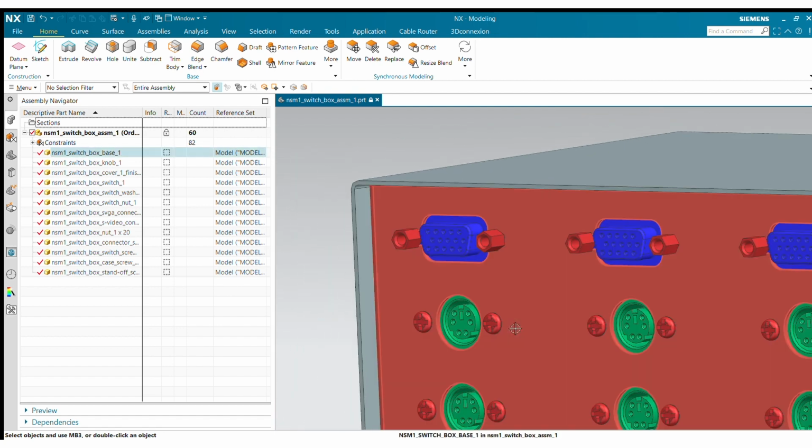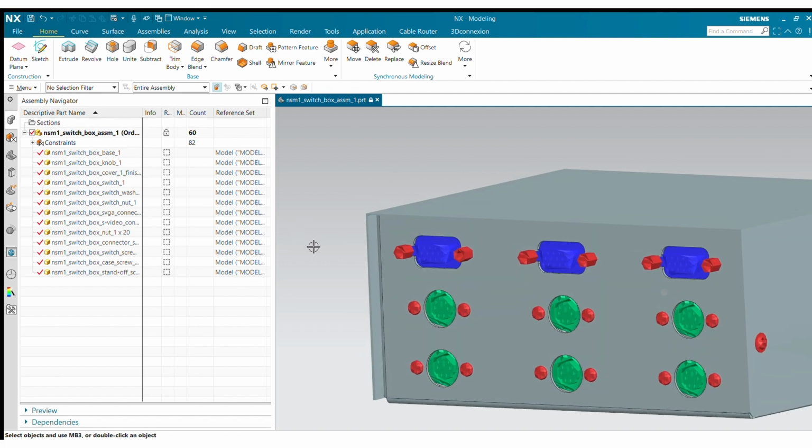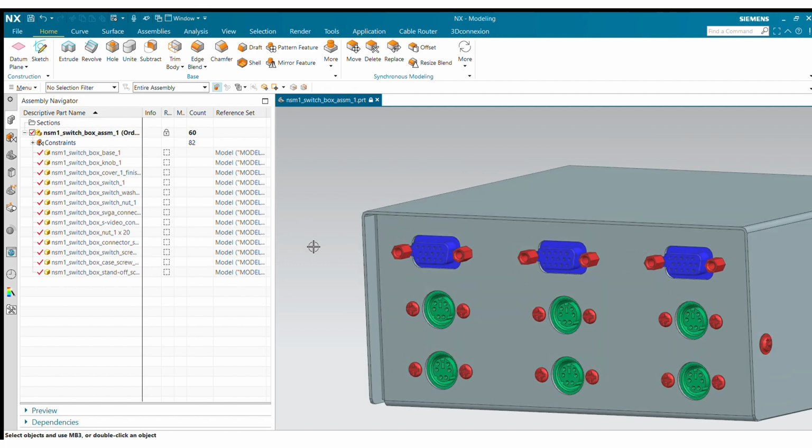So this is helpful if you still want to have your assembly open up quickly, but only focus on a particular part with the exact geometry set on. So you can always hit that show exact button. Okay. So let's say I want to have the same increased edge quality for all my parts.